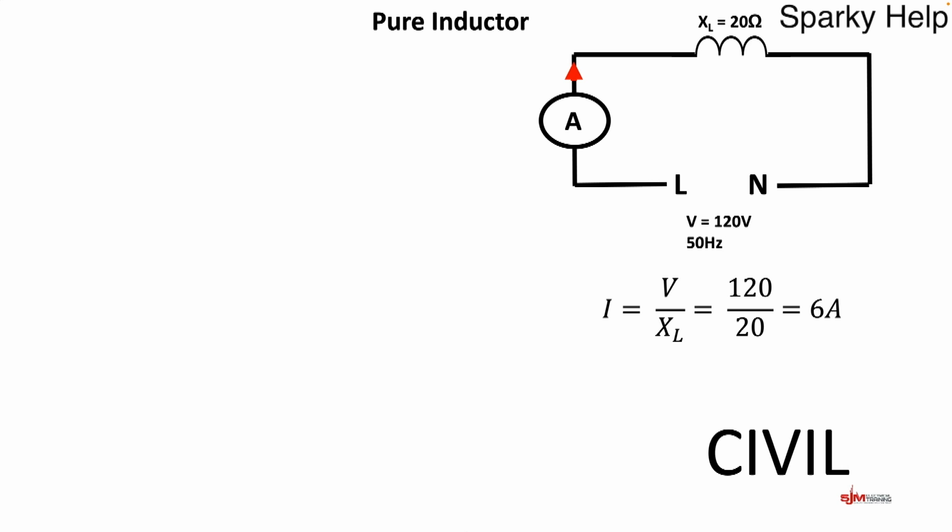To help us with the phasor diagrams, we can use this word here, CIVIL. How does that help us? Well, we're going to look at only 3 letters in this particular word. And this is an inductive circuit, so we're going to look at the last 3, which is VIL. L being inductive. The V in this case stands for voltage, and the I, well, you guessed it, I hope, that stands for current. And if we look at this, then V is in front of I in L. So in an inductive circuit, V leads current. And that's basically how we'd look at this one.